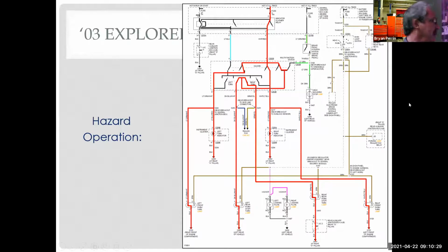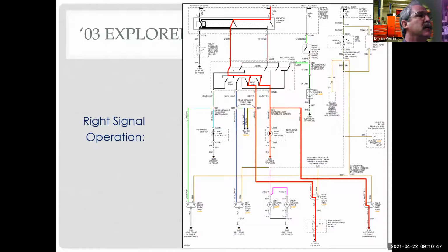Are you kind of following the thought process here a little bit? So here's where we're going to compare and figure out what is most likely not the problem, and then look at what we use in every one. So we don't use that there. And if I use the brake lights, oops, I'm sorry, that's right turn signal operation. Right turn signal operation, I'm only using the right turn signal. So if I go to left turn signal operation, I would only use these two bulbs. So it can't be these bulbs because I don't have a problem when I use those bulbs.